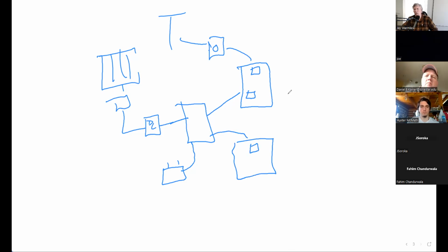Some of my circuits are going to be output from this panel, the non-critical circuits, the ones I don't care about if the grid goes down, like hopefully my garage door opener and maybe the bedroom outlets or something like that. Here we're going to hook in our refrigerator, our freezer, our well pump, outlets in the kitchen, whatever you've determined as being critical.